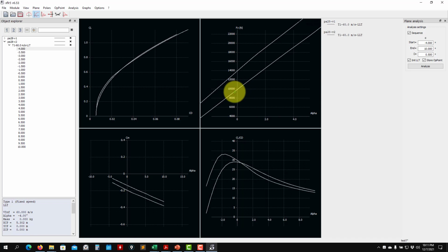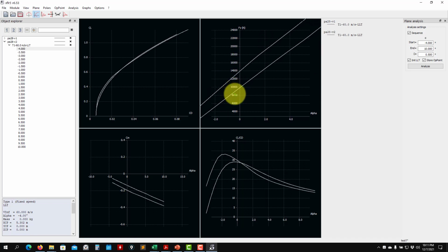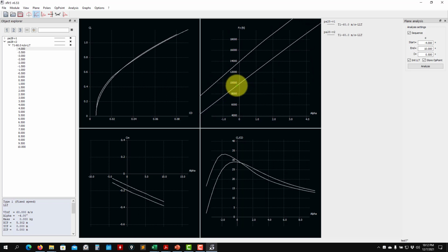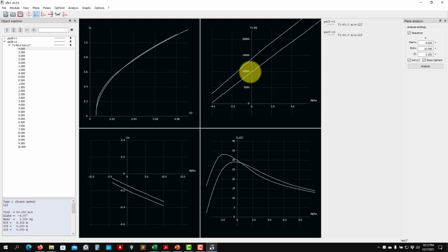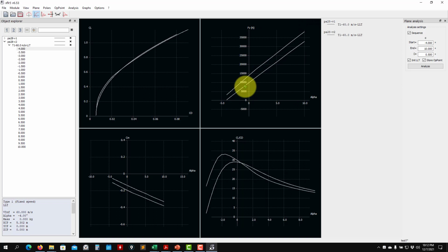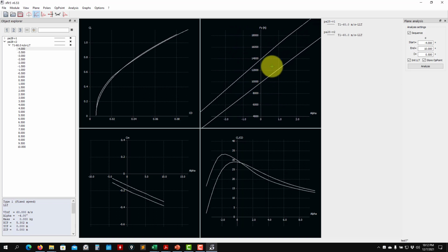Okay, well, not much worse. Okay, but probably it will be better in terms of if I want to have my cruise condition at 0, it is better. But if I want to have a larger angle here, when in CL0, it's better to use the other airfoil. Okay, but see that with different airfoils, we get the same behavior, and see that in this case is the decided behavior. No, 0 angle here. The LD corresponds to the maximum. This is ideal. This is what we want.